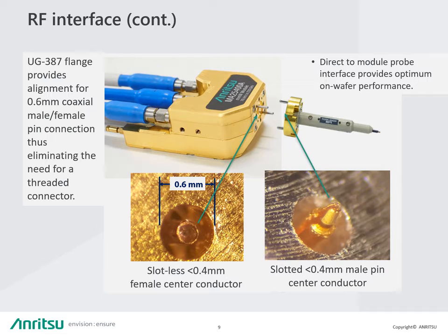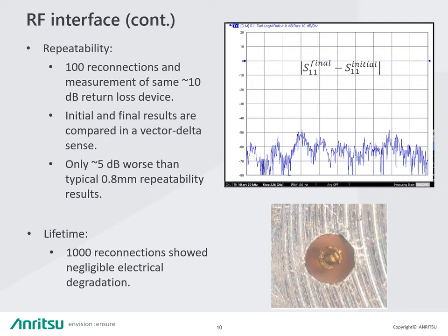The other change and modification we made was to slot the male pin instead of the female pin. This gave us the advantage of better durability and reliability over multiple connections. The end result of this new design is a connector with very good repeatability over a lifetime of connections.